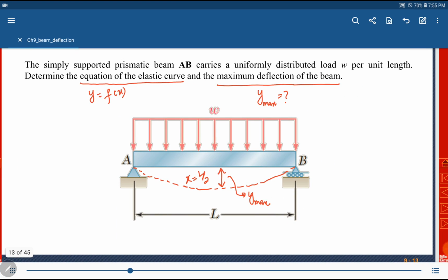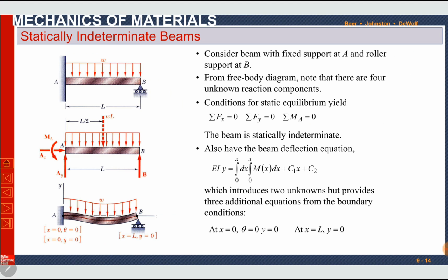Moving further, our next topic is statically indeterminate beams. Up till now we have solved statically determinate beams. Now we are moving towards the solution of statically indeterminate beams. Statically indeterminate beams are those beams which have more unknown reaction forces than the number of equilibrium equations we have. For two-dimensional problems, we have maximum 3 equilibrium equations: summation of forces in x, summation of forces in y, and summation of moments equal to 0.